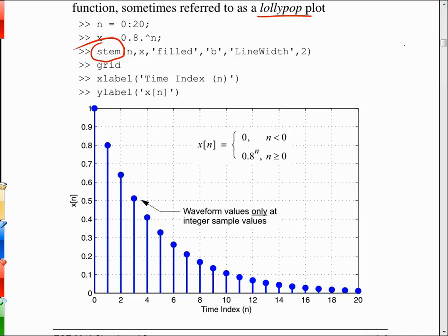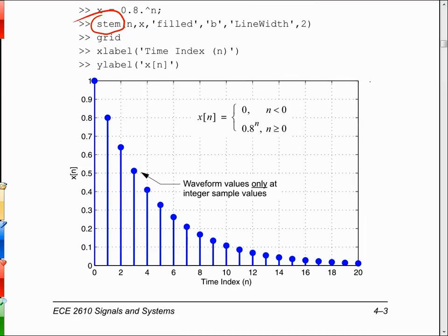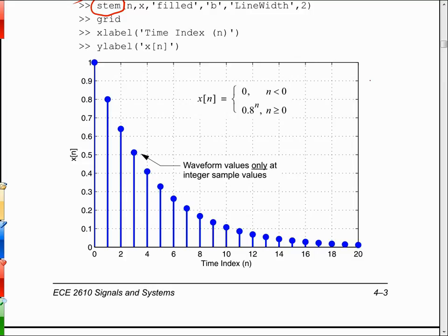And a good case in point might be in a car. At one time, I think the speed control was probably all done in an analog fashion. I think today it's done in the discrete time domain where the signal values are sampled with some microcontroller or DSP on board the car, and then it's a sequence, and then there's filtering done, and then there's an algorithm that brings in data from the stick on the steering wheel where you set points.